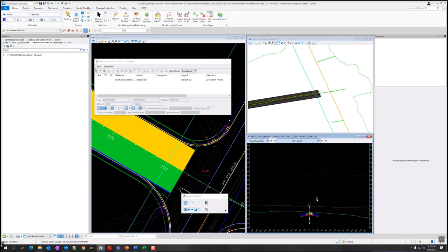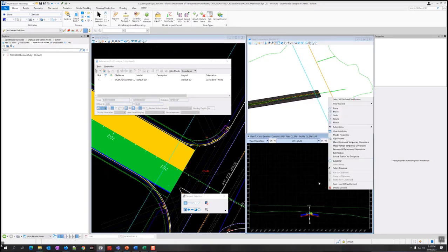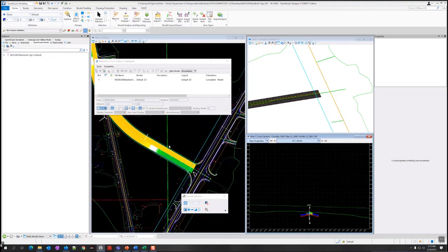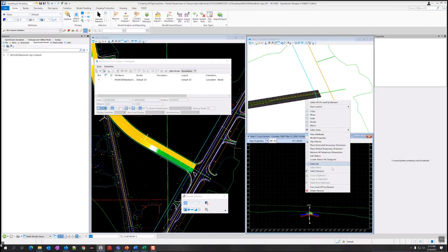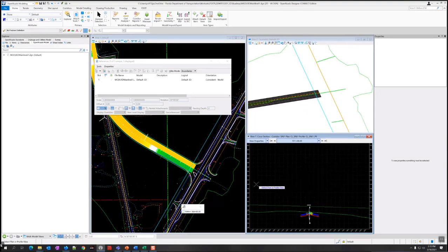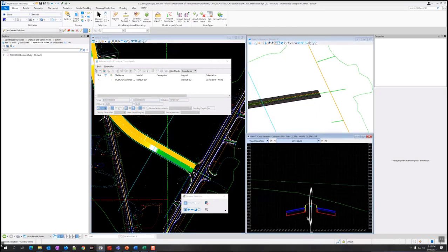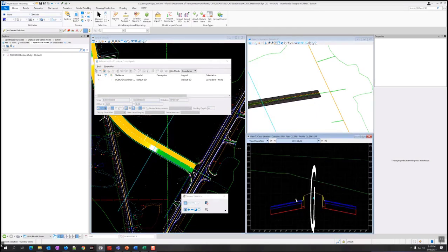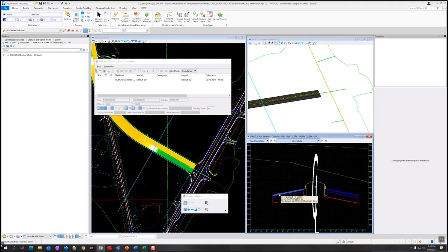And if I move forward, it would be tedious to do it one by one, but I can do it one by one here. I'm going to right click here and do locate station via data point. And I'm going to come over here in view 1 and come over here around the transition area. And you can see no super yet. We haven't applied anything. All we did was reference it in. So you can see it's a normal crown, which is fine.